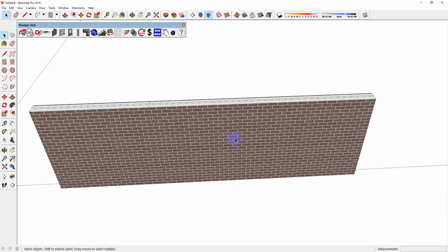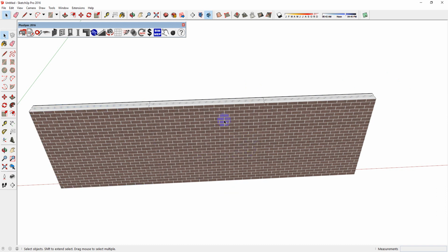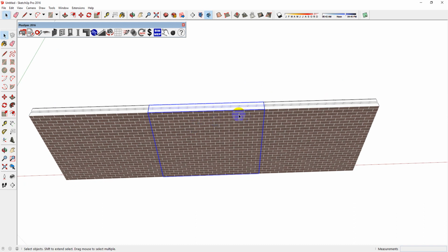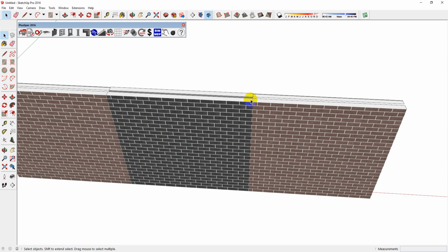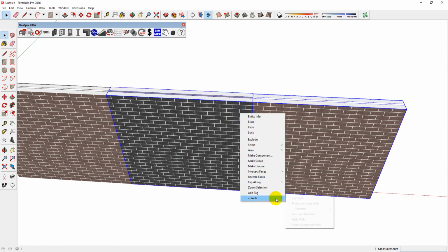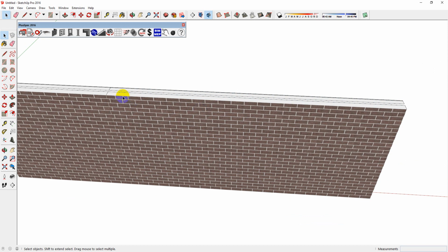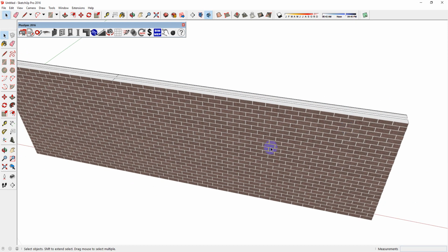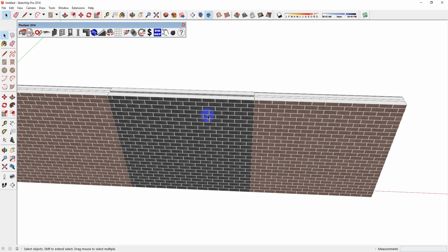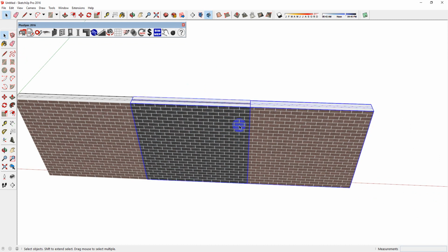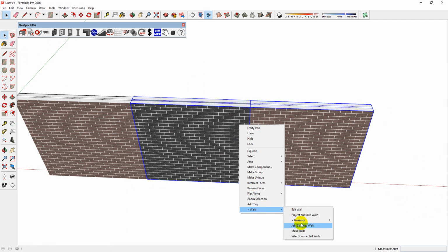Let's go back a couple of steps so I can explain this further. And now I'm going to change this to a different construction type and a different material. Let's choose a double brick wall. Let's go through that again. If I select meld walls, it's actually going to change the double brick wall into this brick veneer and forget that it was an individual wall type. That's why you're better off choosing join wall for this instance.